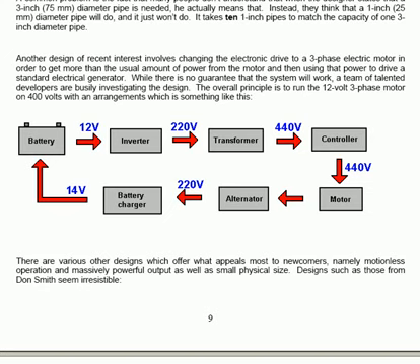That is then passed to a controller which feeds the 440 volts to the 3-phase motor, which drives the alternator, and then that is dropped down to give an output to a battery charger which produces 800 watts at 14 volts to feed the junction between the battery and the inverter. So the inverter, after the few seconds of startup, is actually powered by the alternator itself.